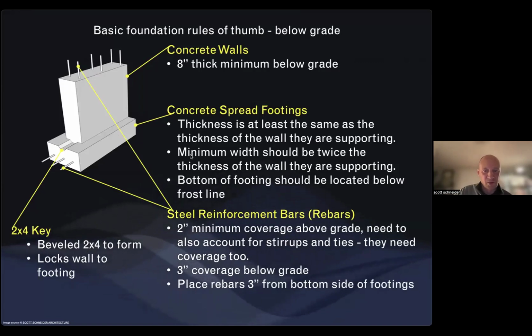And if you're in an area where the ground freezes, you want your footing to be about 12 inches below the frost line, so that when the ground is freezing or thawing, it's not affecting your foundation by moving it.